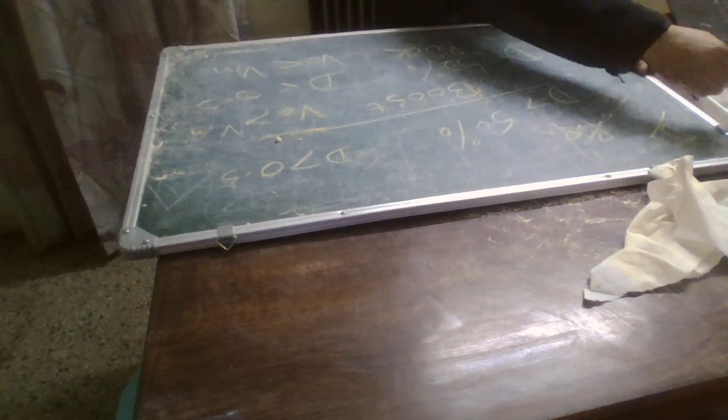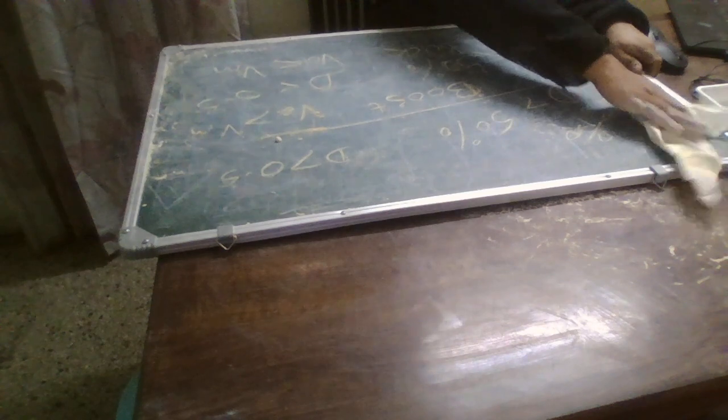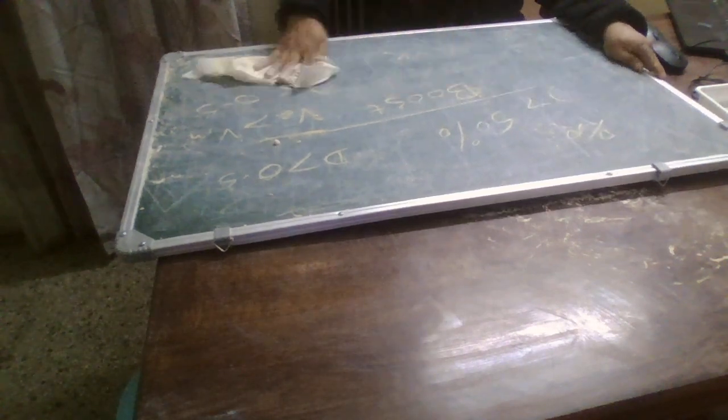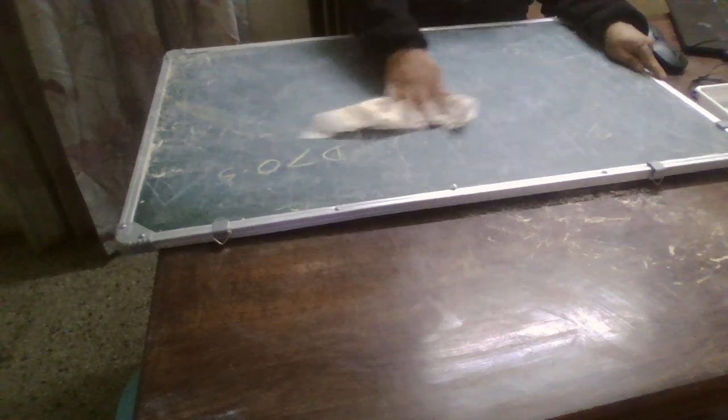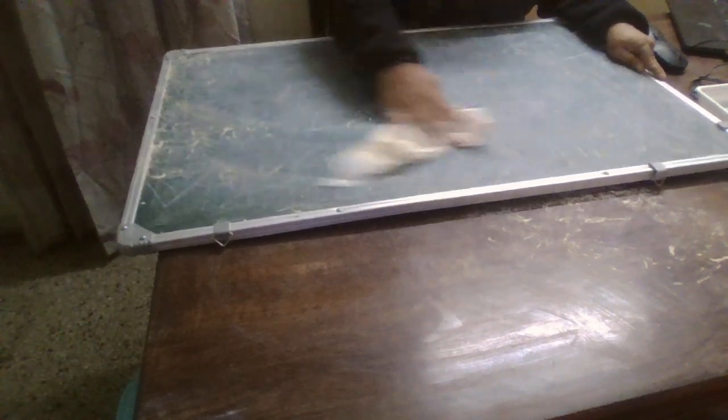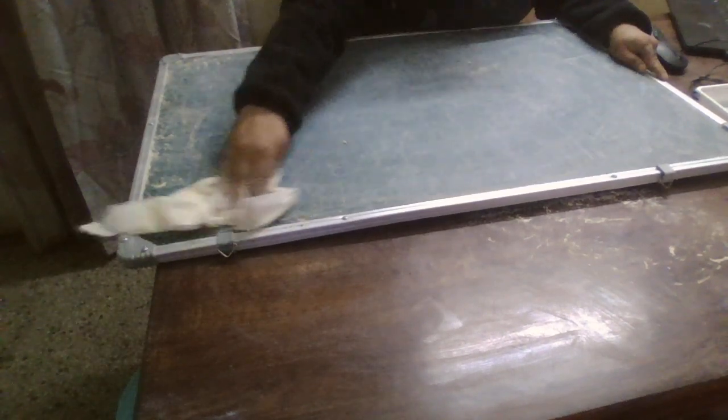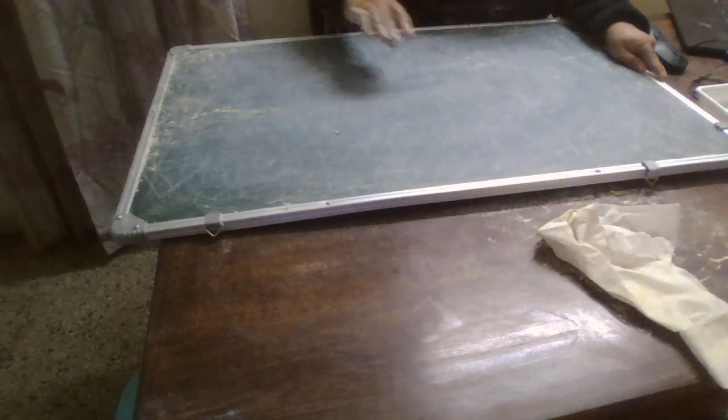And this point will be used in the flyback converter video, because we can use a flyback transformer as a buck boost, since it's derived from the buck boost only. We can make it work in a strictly boost configuration and also in the buck configuration.